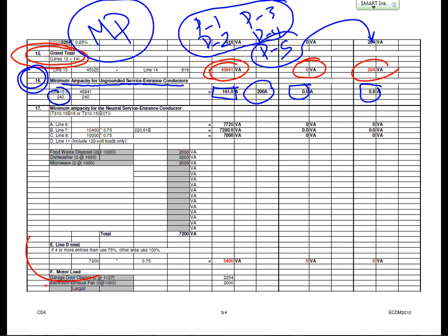When you design a building, guys, the worst thing that could happen is a 50 amp panel here and a 60 amp panel here. That's called splitting hair. You want to standardize when you get into a building. So if one of them is 50 and the other is 60 and the other is 90, make 100 amp panels all across the whole building. Standardize your design. So you walk into this building, most likely each one of the apartments has a 100 amp panel based on the calculation. Okay, any comments, any questions?